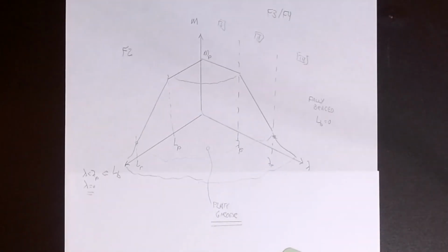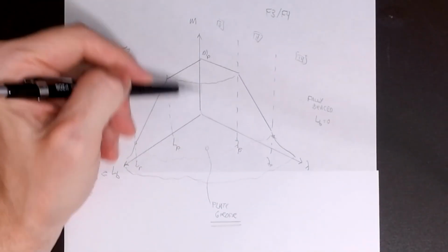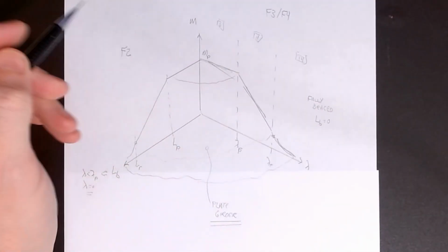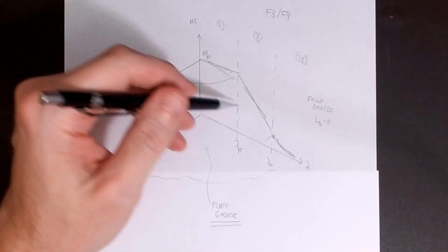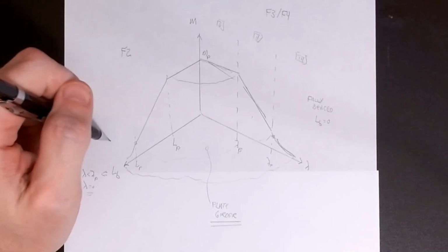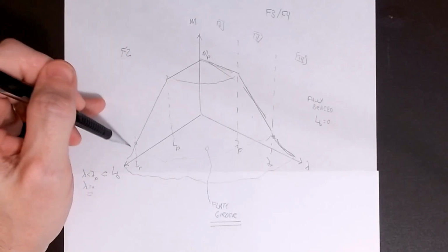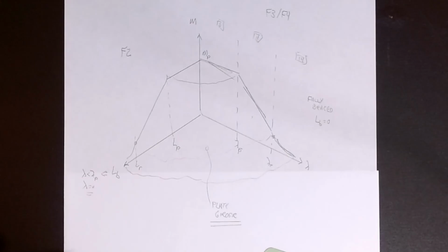The graphic I showed you here is the exact same curve as what you saw on this axis. It was this line and that line and this line. It's the exact same curve. That's the way we look at it. It's just that now we're going to draw curves for this one, as well, and when we get to lateral torsional buckling and unbraced length, we'll be drawing another one that's similar with some other values. But it's very, very similar. So if you can remember this graphic, it will tell you the story. Everything is about figuring out what region you are in.